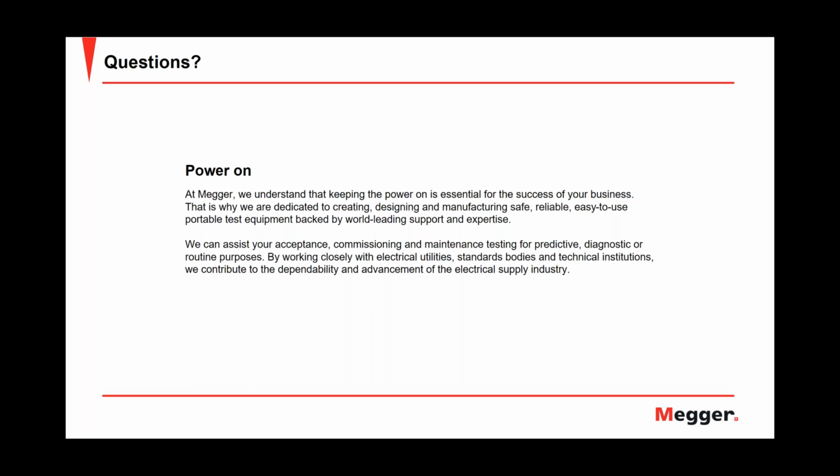All right, excellent. While I have you, the next question is also going to be directed at you. Are the presented fault locating methods also applicable to 132 kilovolt cables? Okay, so first of all, Javier had an example where he used a typical portable medium voltage fault location system on a 230 kV cable. So, as an engineer, the answer would be it depends. In the case of the example that Javier had, it worked very well.